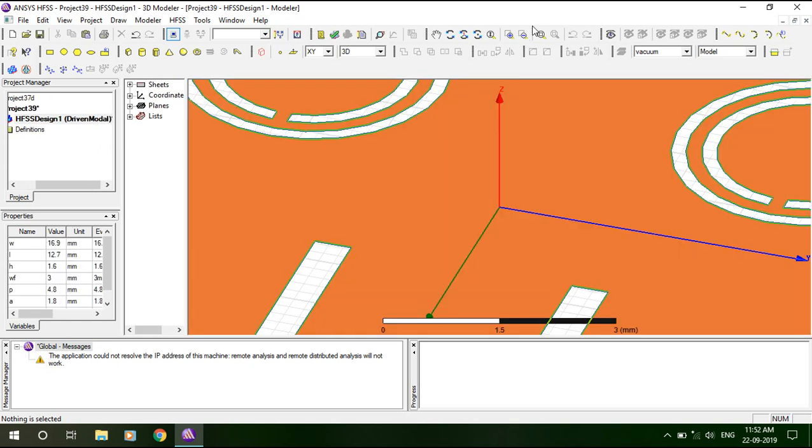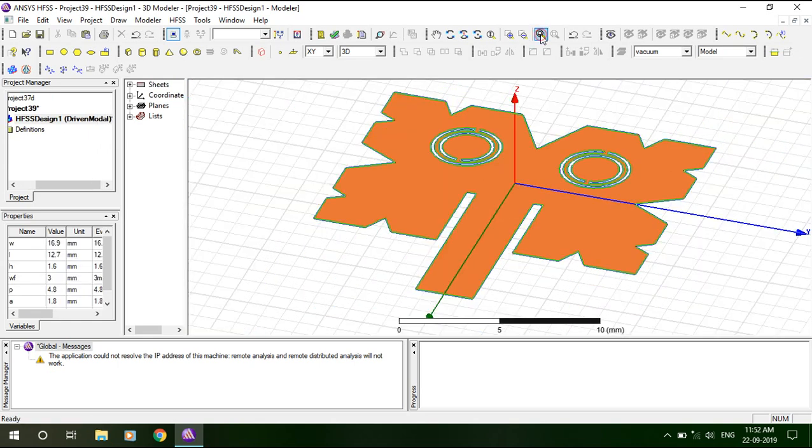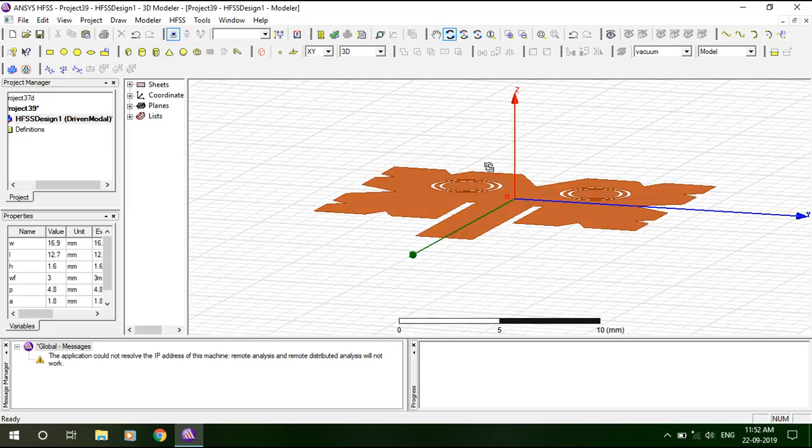I am doing this because this will not affect your original design, because sometimes changing the dimensions and all makes the solutions invalidated. So this is the best process for exporting DXF files. This will not disturb your original design. Whatever is there, you just copy and paste it to a new design.